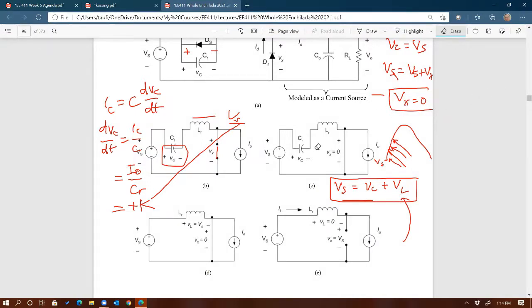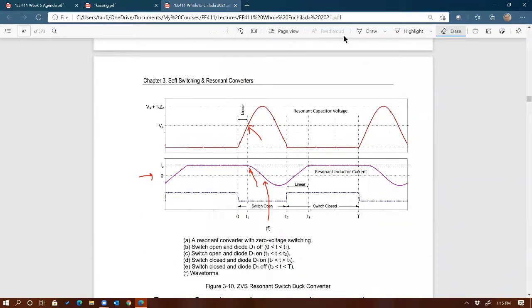Okay, so now let's see what's happening here. We have voltage across the cap that goes as a sine wave, right here. I'm just going to show you the picture here. It follows the sine wave, and then it's going to reach its peak value, and then now it's going to start to come down, meaning now the capacitor is discharging, because the slope is negative right there. So I know that right after that peak value, the capacitor starts to discharge, right?